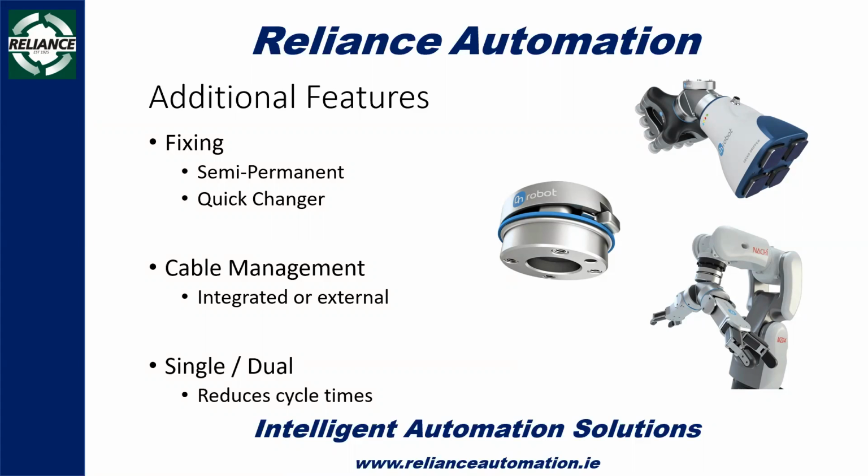And then how many grippers you want for your application. An awful lot of the time, a single gripper is perfectly adequate, whereas there are some applications, such as CNC tending, where it can be beneficial to have two grippers so you can both pick up a part and load a part in the same movement. And that's going to depend on the cycle time of your application as to how much return on investment you get from that.